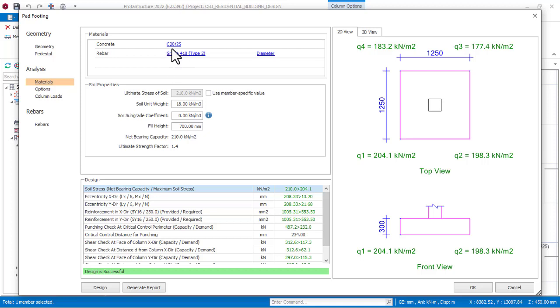This first one here is simply called cylinder strength, and this one here is called cube strength. What we use for the design of structure is cube strength. Cylinder strength is just for experimental values and all that. So we use cube strength for our design. So basically right now I am using concrete grade 25 for the design of this foundation, while for the superstructure members I use grade 20. Okay, now once you do that, leave your steel as it is, 410.